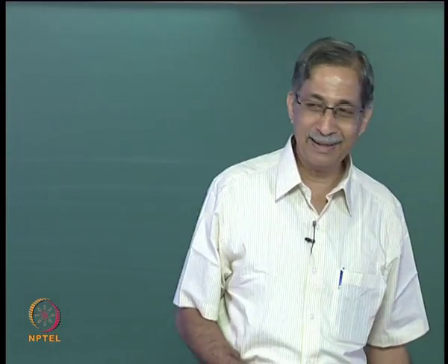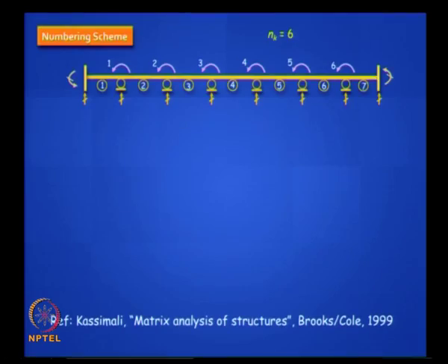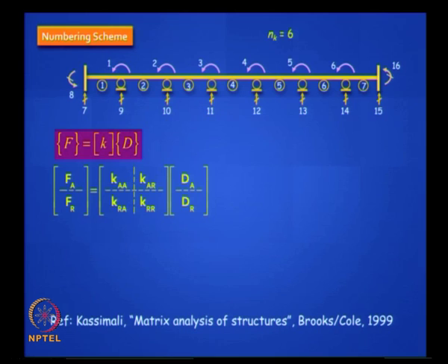So it's important to keep your band small, and there's a measure for it. It's called bandwidth or half bandwidth, and these are your restrained degrees of freedom. So let's just look at the active degrees of freedom. You forget about the restrained degrees of freedom. Incidentally, you can partition your K matrix into active and restrained components using these notations.